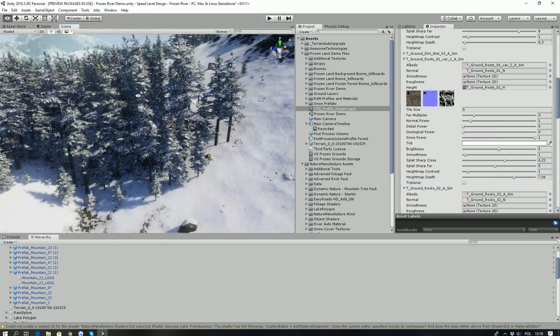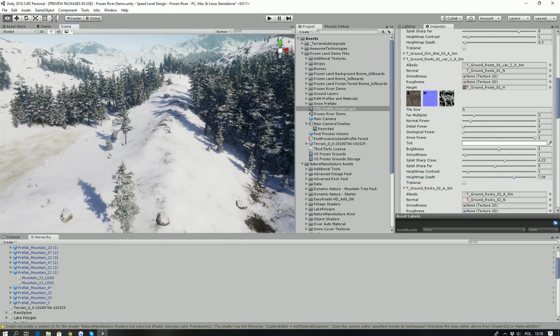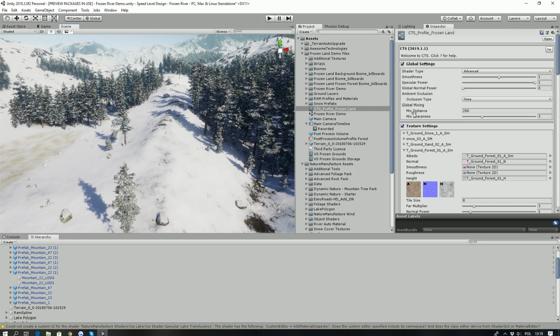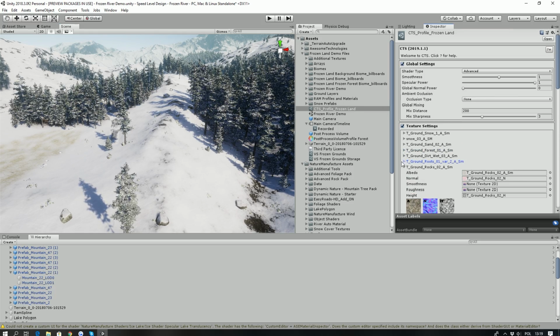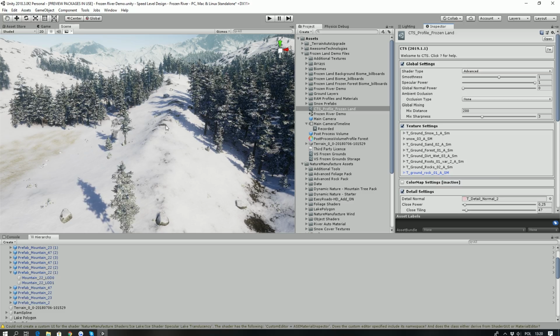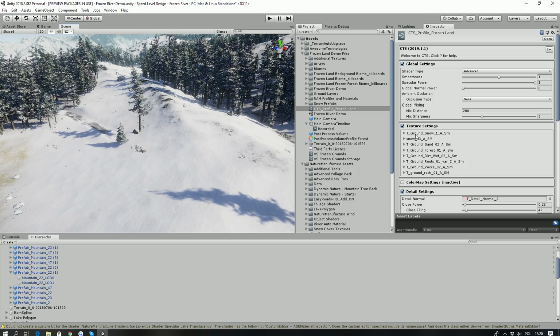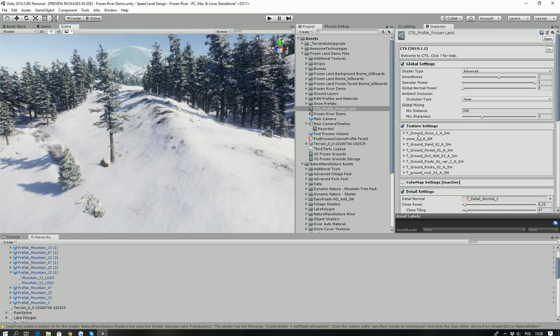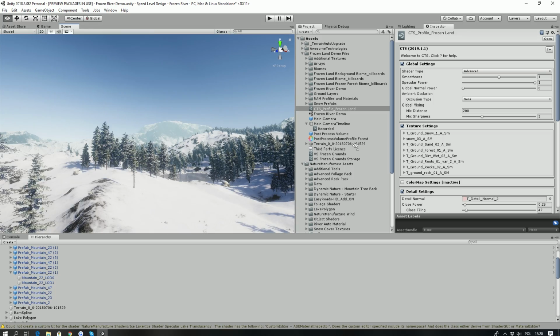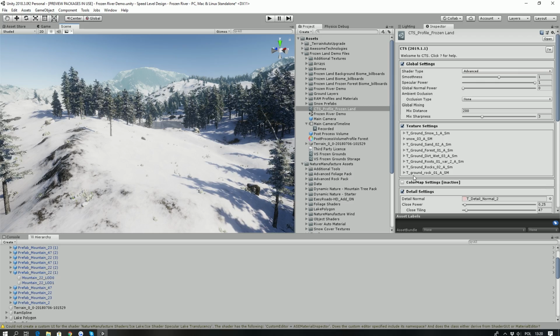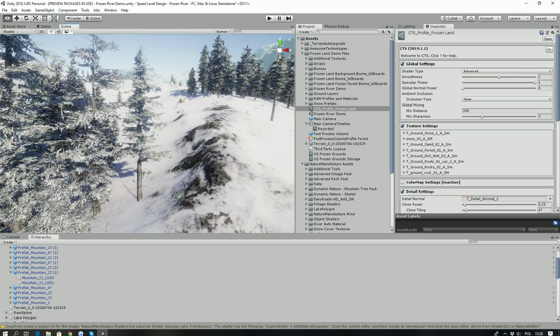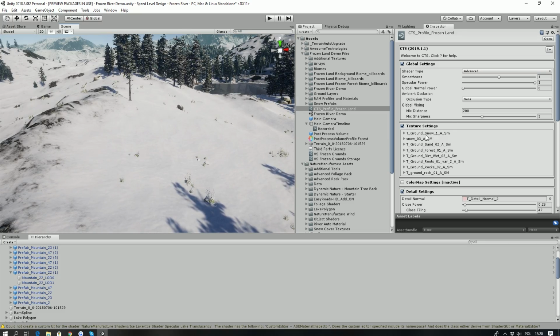The main idea and rule about height blending in CTS is that you have to put textures in the correct order. You should start from textures with low granulate like sand and snow, and then end on big surfaces like rocks, for example. If you hold this, the whole blending will work very naturally. You will see this gives a lot in your scene. It's truly the best way to get the best result with CTS.